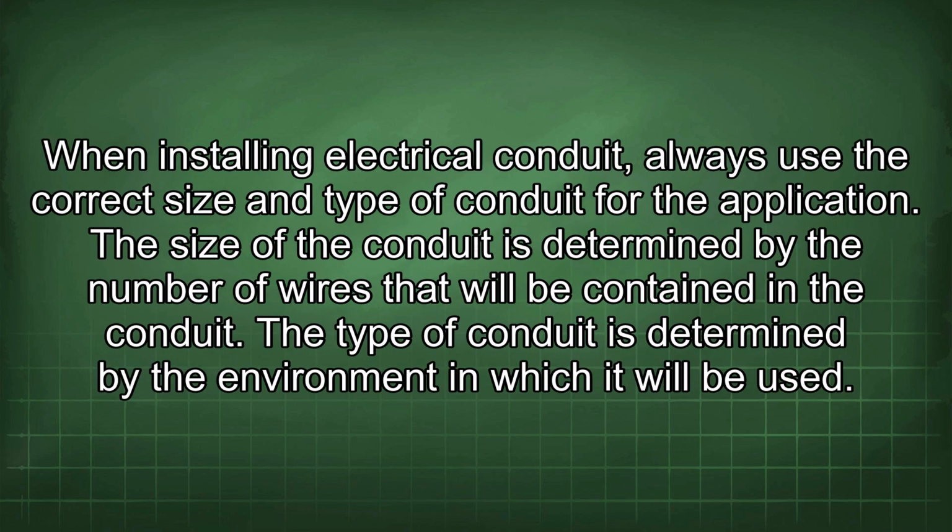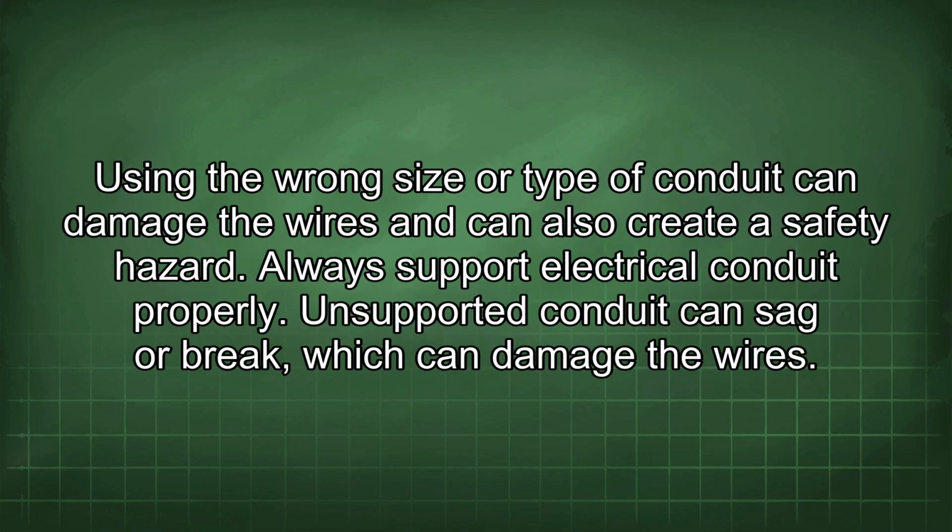When installing electrical conduit, always use the correct size and type of conduit for the application. The size of the conduit is determined by the number of wires that will be contained in the conduit. The type of conduit is determined by the environment in which it will be used. Using the wrong size or type of conduit can damage the wires and can also create a safety hazard.